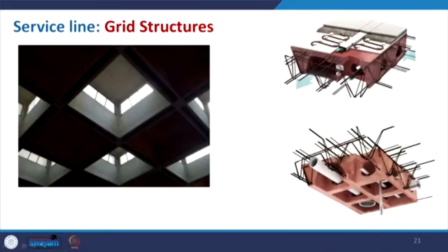Now, so as to align the services, which is very important for the flat slab, we also put the reinforcement, and then we try to make the false ceiling to cover it. But because it has a depth, and sometimes if that can be done with the mold, especially if this is designed, then all the services can be fixed within that. So, this is one example where the pipelines can go, and here also you can see the electrical fittings, how they can be adjusted within that section.